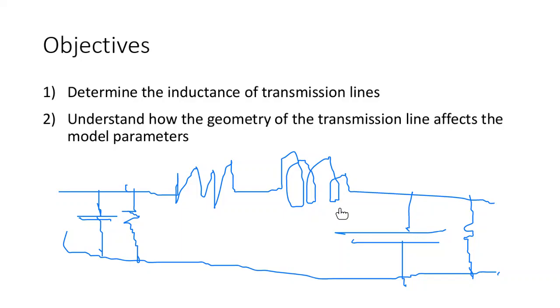That's why we need to present it. We have charging current, as we can see later. Therefore, we need to put a capacitance. What capacitance represents is the charging current. So we have also current between the transmission line and the earth, from earth to the transmission line, and it depends.